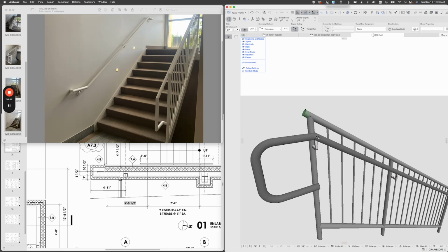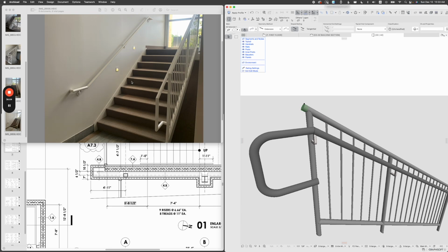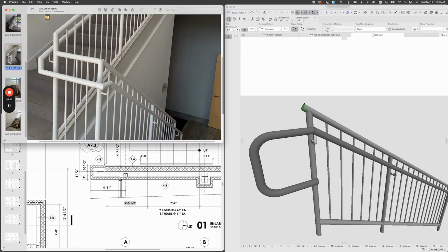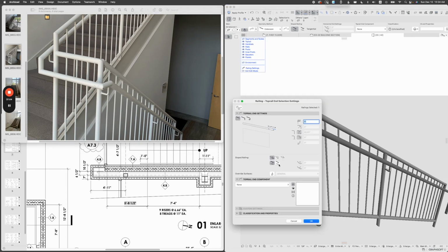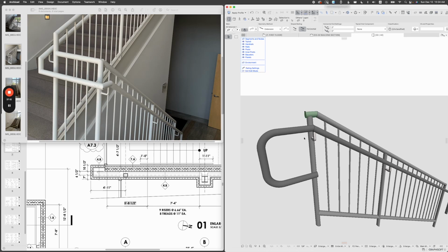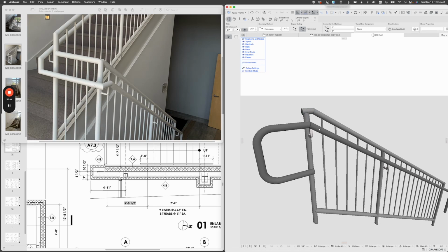And I need to turn this a little bit. So I would go here, and this time I would pick this sloped railing to horizontal, and I can even extend it by maybe 2 inches for right now, and just leave it for now.